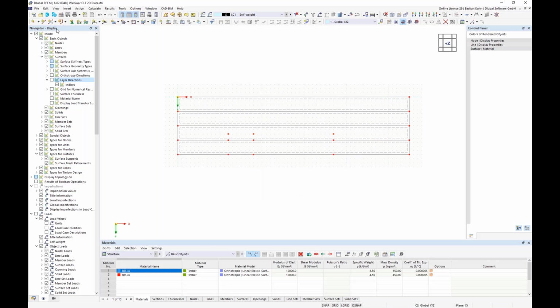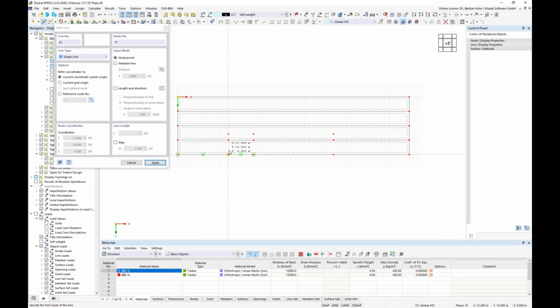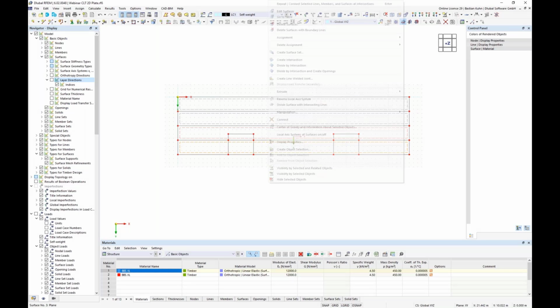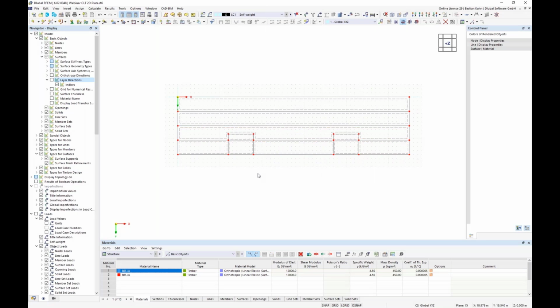Say okay, and then I have it there, and then I will draw a few lines in here and there. And this one I will be copying via drag and drop onto the right side. Okay. I will connect the lines in here, and then it's okay. And then a very nice function is, if you right click in here, you can divide the surfaces by integrating lines. And now you can just delete the surfaces which we do not need.